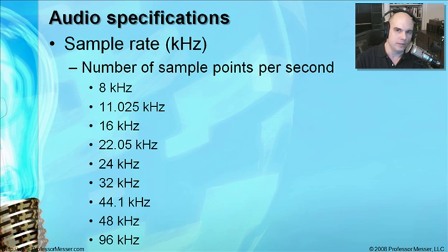Remember, audio, and this voice that you hear right now coming out of my mouth, is an analog signal. It's not digital. What your computer does is separate out over a second time period 8,000 little chunks, and it stores each one of those as an individual digital amount, a digital value.